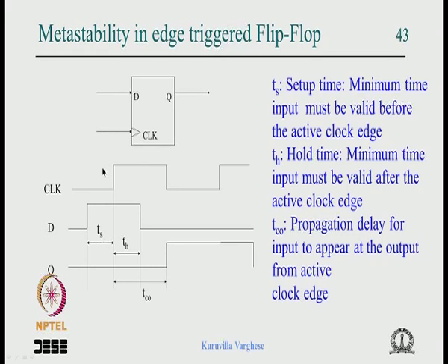We have learned that the master is enabled during the negative clock period and the slave is enabled during the positive clock period. So there will be inverters in the clock path. Normally you will have the master latch delay minus the inverter delay as the setup time, because that is the latest a master latch can set before the clock edge happens.